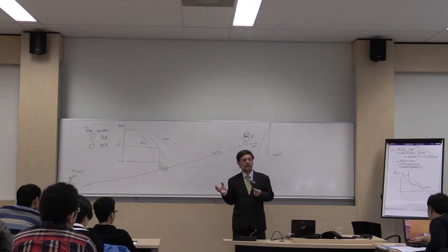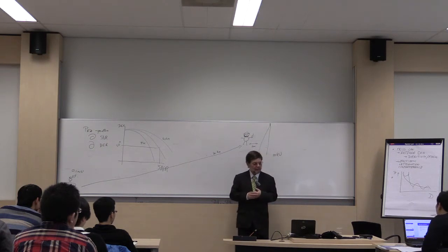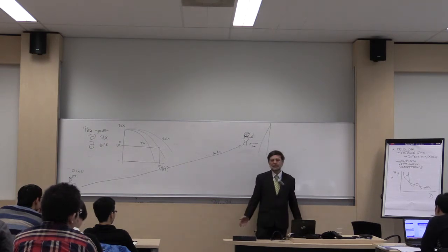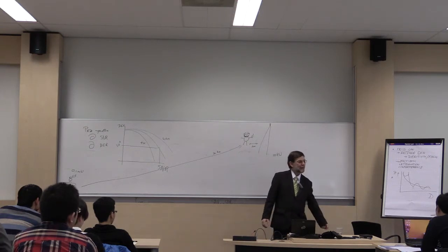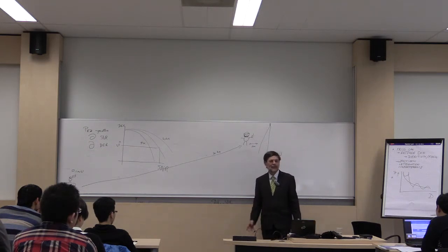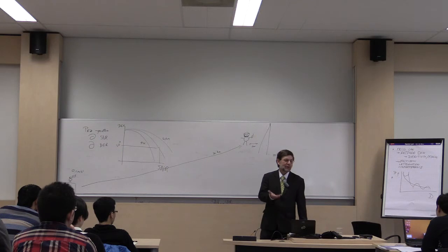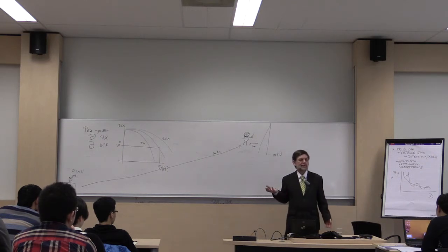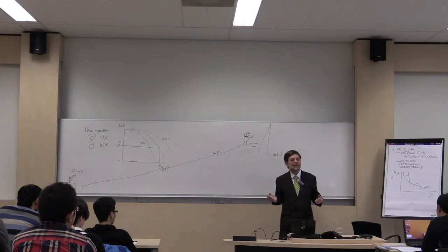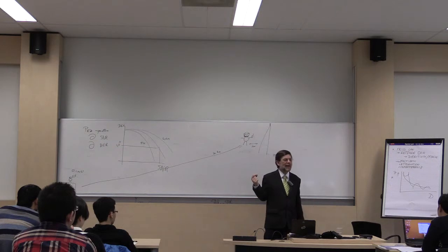Because people are used to radios. You can always break a radio. You can always find a situation where a radio is not working. Very famous case: people have these nice desks with metal drawers underneath, and people put their cell phone in a metal drawer. It's not good for your received signal strength, because it's like a Faraday cage. They put it on top of their laptop. It's not good for interference. But also people know that in some cases the reception is bad, and they just accept it, and they move a little bit away, or they put the phone somewhere else, and suddenly it works again. They might not understand exactly why, but it's because of this.